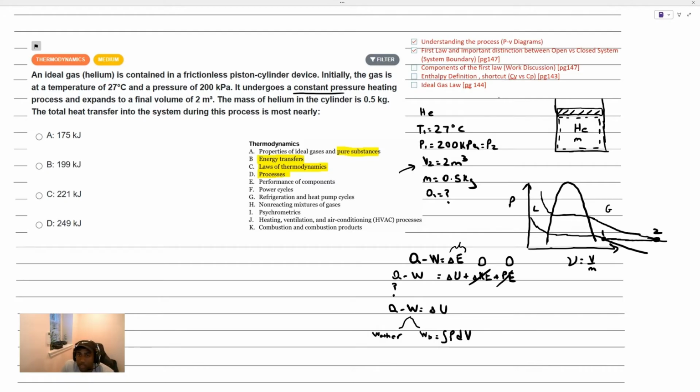It's the work attributed to expanding or contracting a boundary. And you can see that in this case, that's very applicable to us because as that piston here is rising up, you can see that our boundary is expanding. We expect to have some boundary work in this case.